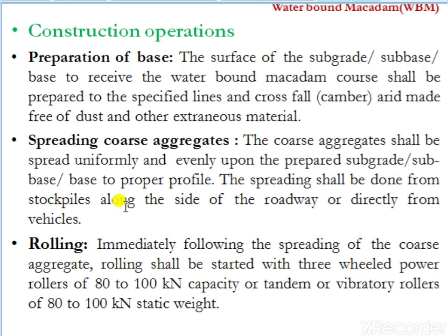If it is necessary, the aggregates can be sprinkled with water, and after this, the aggregates have to be compacted by passing the roller over the spread coarse aggregate.